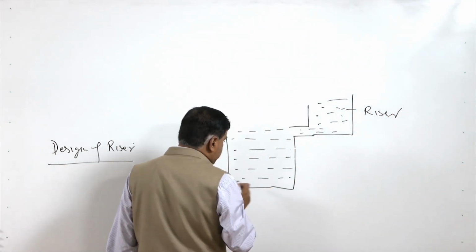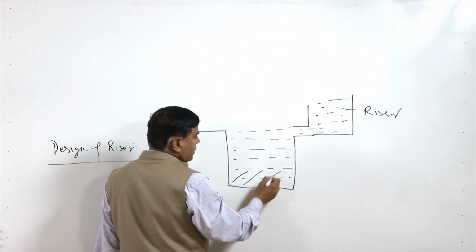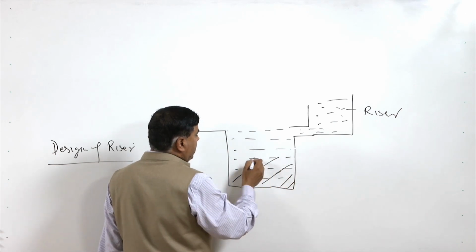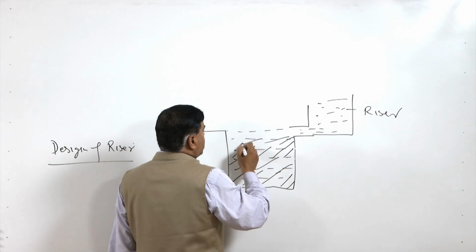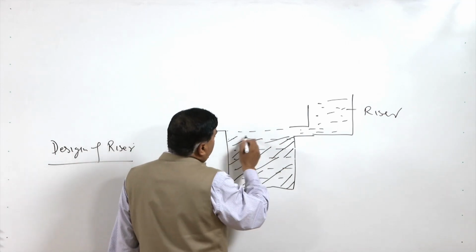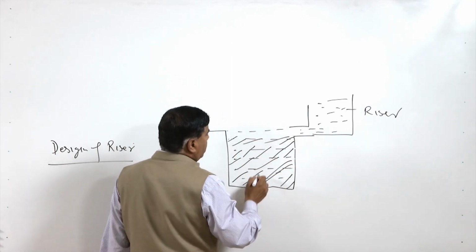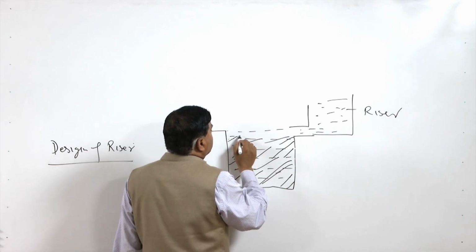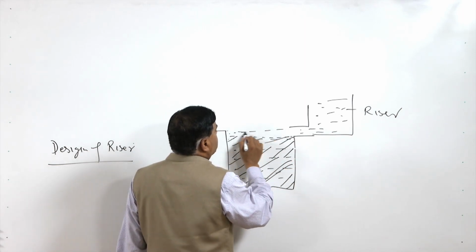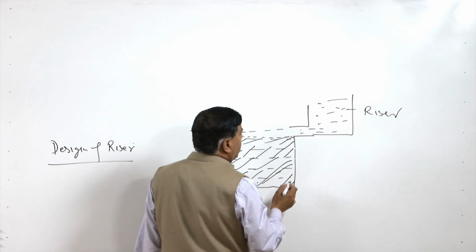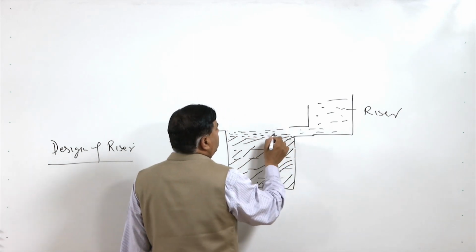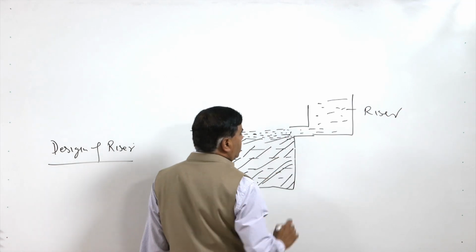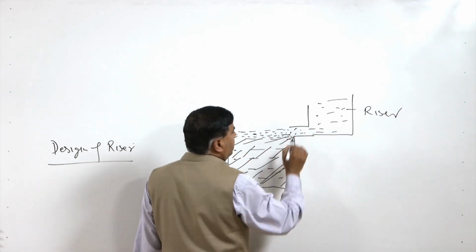It is expected that the solidification of the molten metal will take place first in the mold. Once this solidification is over, whatever shrinkage due to this transformation has occurred will be left at the top. That volume of metal which is deficient due to the shrinkage is to be fed from the riser.